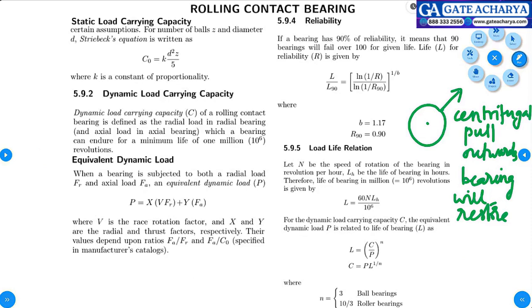So when we sell components based on this finite life, we will take one component, run it in the laboratory, switch on the motor, and finally note down how many cycles it has come. Then whatever we manufacture, we give as a specification: 90% of life, 80% of life, 70% of life. That is why we are doing this. We need to have an idea.